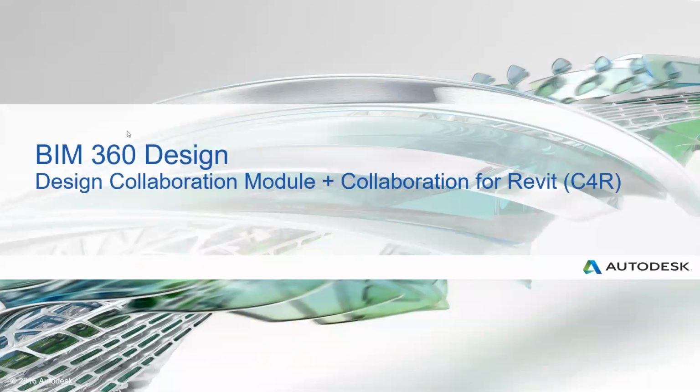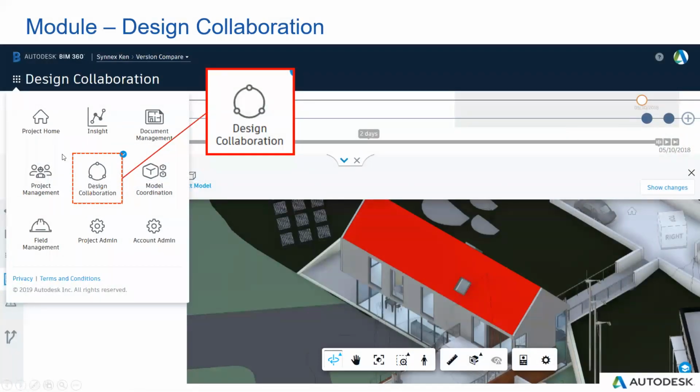When you use BIM 360 Design, you have to remember we have two or three things. The first one is Revit 2019. The second thing is the design collaboration module, but in this practice we don't need to use this one, just ignore it. The other one is Collaboration for Revit, also named C4R, for you to synchronize your Revit model to the cloud. In the BIM 360 website, it will show the design collaboration here.